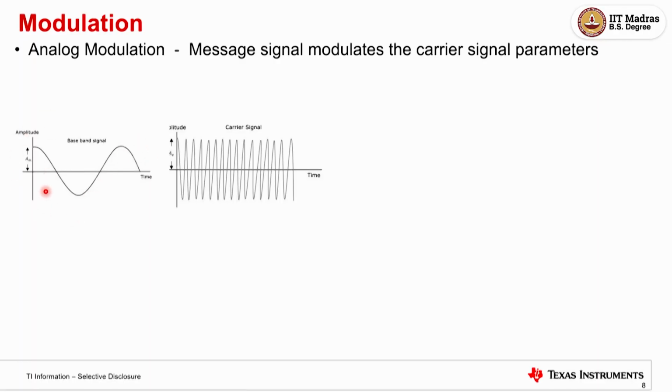So assume this is your voice signal. I'm just taking it as a sine. Somebody is just singing in a particular tone, so that's one piece of information, and this is what we said is a carrier signal that we want to use, for antenna size, let's say. This is a very high frequency. It shows that it's moving faster, so it's high frequency. This is moving slower in time. So somehow I have to send this information, which is what I want to send, packed into this carrier.